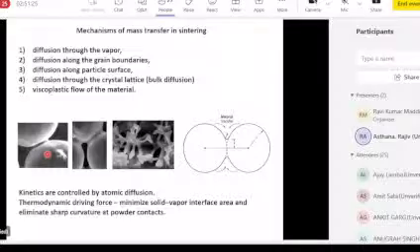But at those temperatures, some of the lower melting point alloying elements could actually melt. So you may end up with what is called a liquid phase sintering process, which is both good and bad. Liquid phase sintering is good because if you have a small amount of liquid forming, the powders will be more tightly drawn together. Just imagine two glass slides with a thin water film in between; they stick better. The same thing happens with powders. A small amount of liquid phase will help densify.